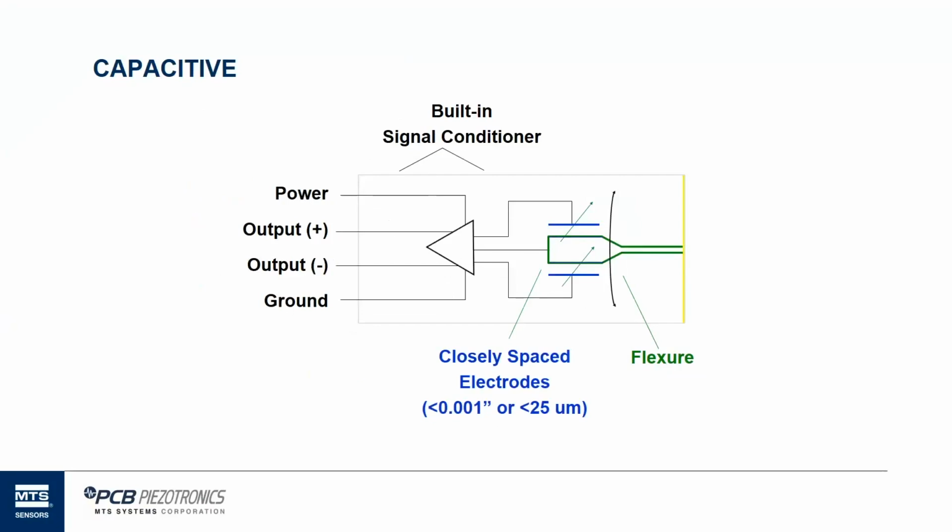And again, this is typically implemented in what we call a MEMS, microelectromechanical machined device. And it's in silicon in very small pieces. And we see down there at the bottom, the electrodes of the capacitors are spaced at thousandths of an inch, 1/1000th of an inch, or 25 micrometers apart. And that's the second implementation of this inertial mass.